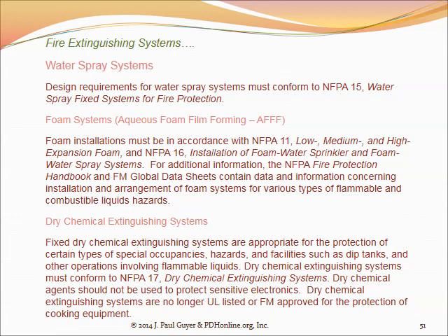And this foam floats on top of the oil fire or fuel fire and smothers it. So this is an extinguishing system that is used in those situations where there's a significant risk, like I say, in an aircraft hangar, of a fuel spill running all over the floor. So this is another extinguishing system.